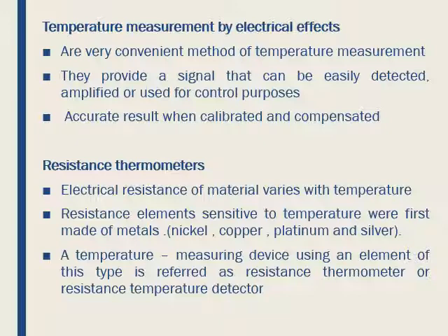However, for regular usage, we use thermometers of the liquid in glass type. The liquid in glass thermometers are the most commonly used temperature measuring devices. The unit consists of a glass envelope, a response liquid, and an indicating scale. The envelope comprises a thick-walled glass tube with a capillary bore and a spherical or cylindrical bulb filled with liquid. The two parts are fused together and the top end of the capillary tube is sealed.